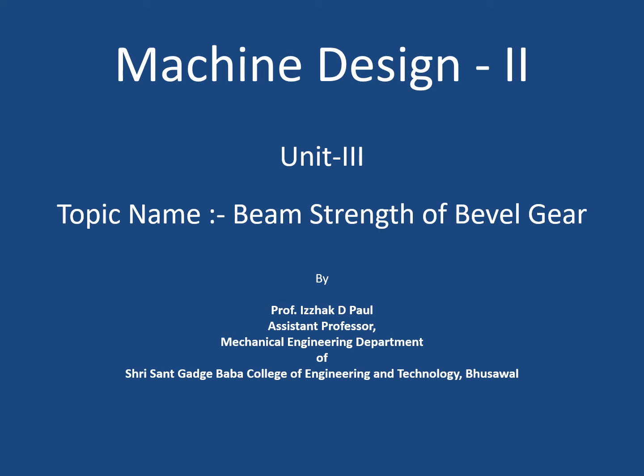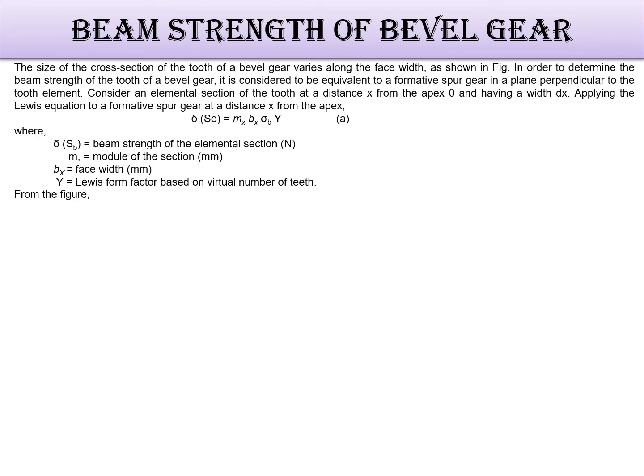So the new topic is the beam strength of the bevel gear. The beam strength of the bevel gear is somewhat different from that of the spur and helical gear. Now, the size of the cross section of the tooth in a bevel gear varies with the face width.